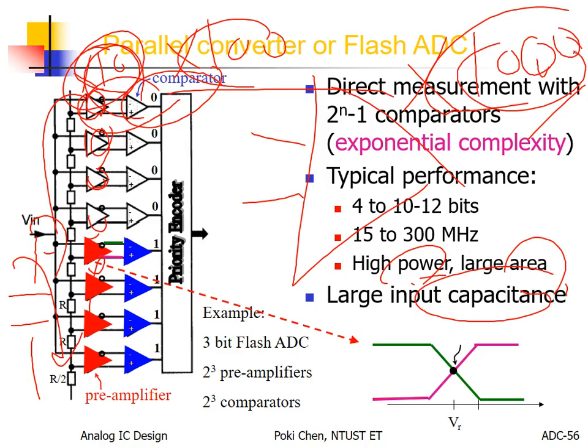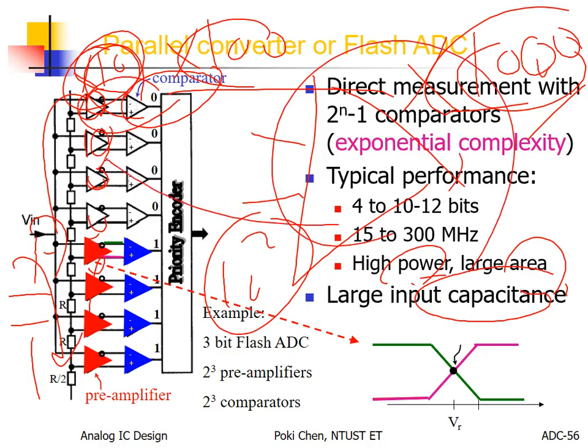Also, I cannot say exactly 100 times, but maybe 2 orders of magnitude area reduction from the single comparator to the preamplifier. It means the parasitic capacitance here will be substantially reduced, compared to the traditional structure with a single comparator or without any preamplifier.